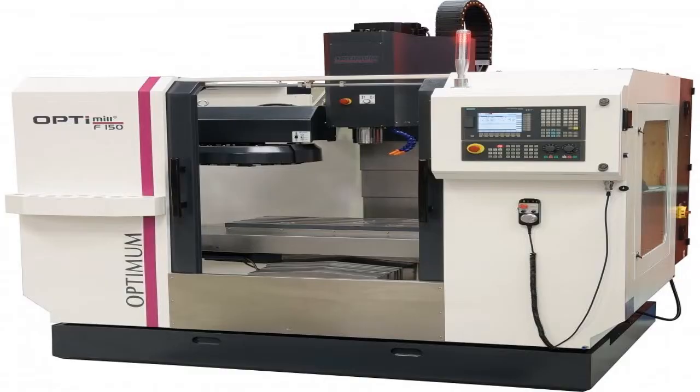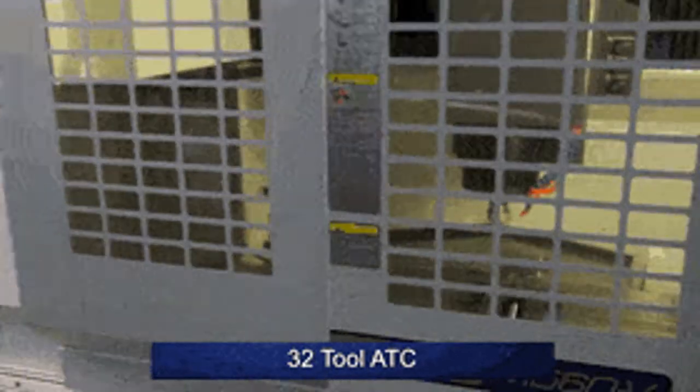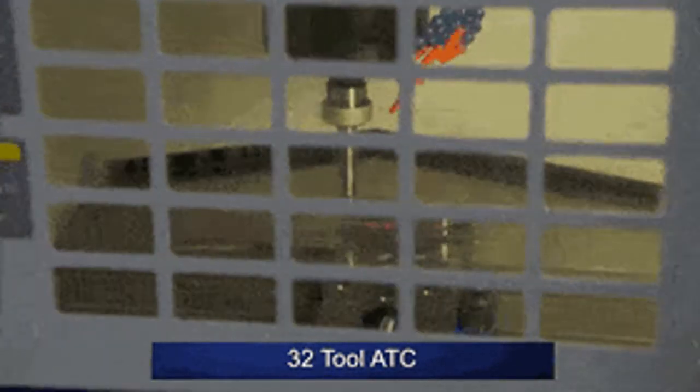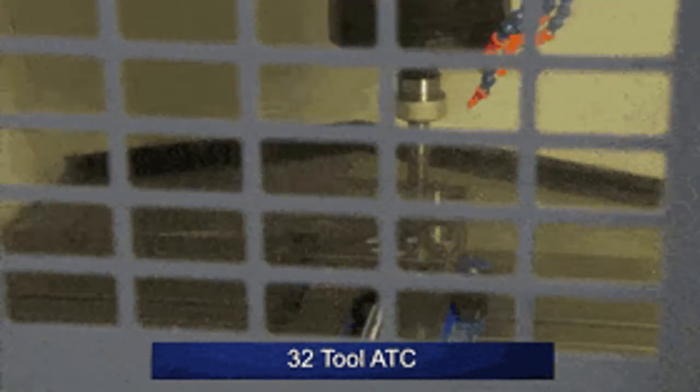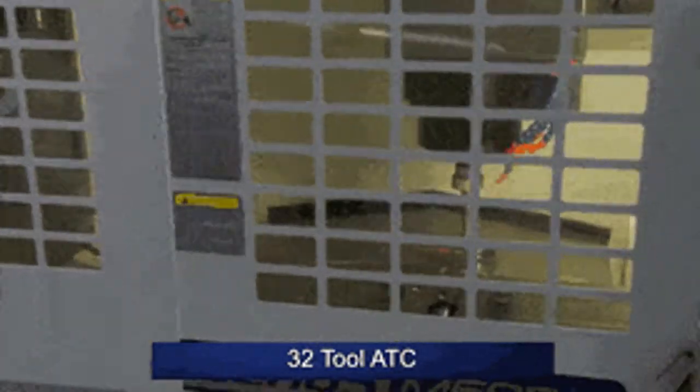The machining center is a highly automated machine tool capable of performing multiple machining operations under computer numerical control in one setup with minimal human intervention. Workers are needed to load and unload the parts. It usually takes considerably less time than the machine cycle time. So one worker may be able to tend more than one machine.